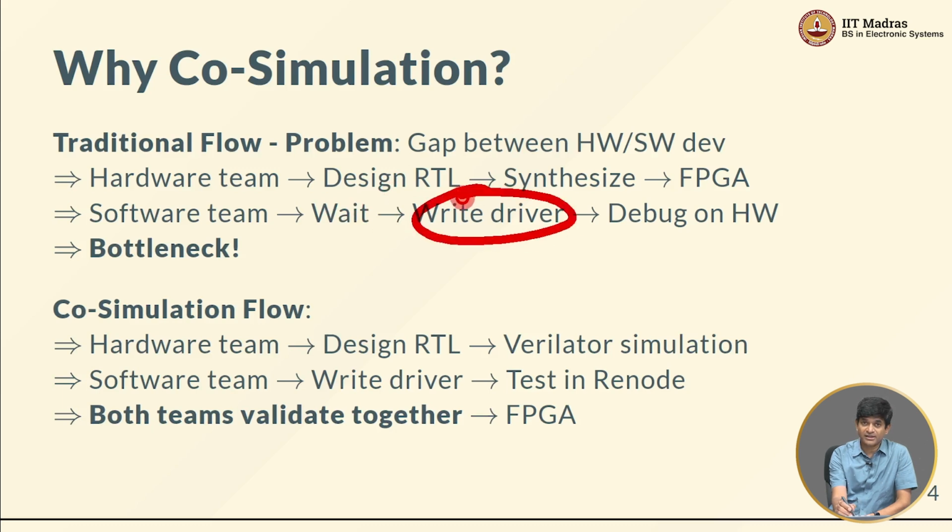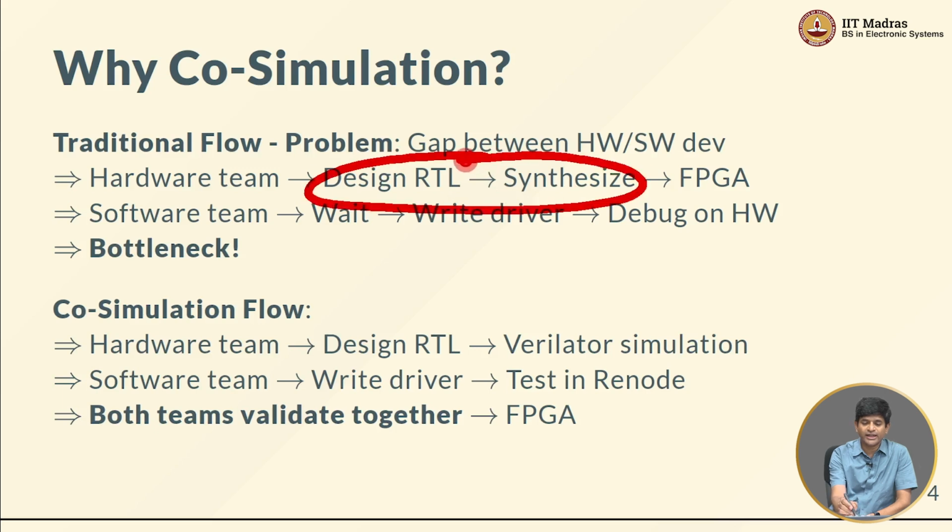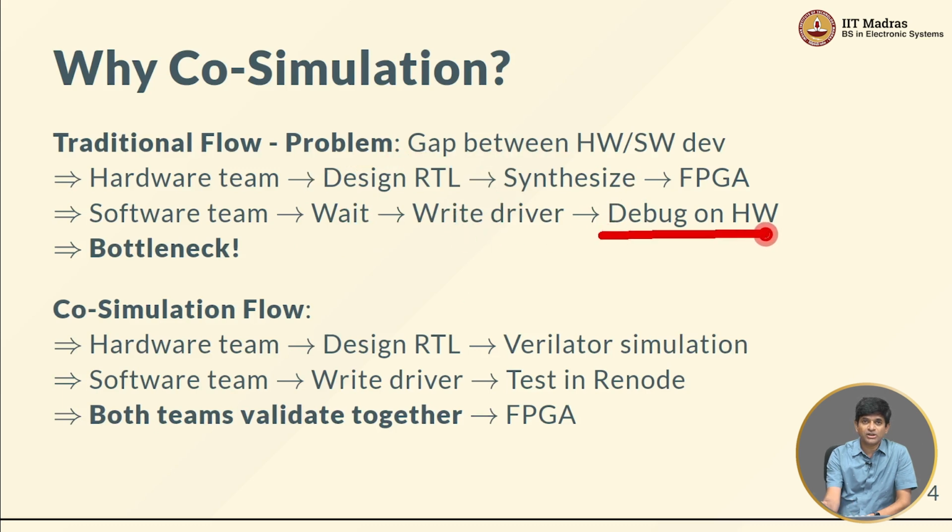But if they write the driver too early, once again they wait, because designing, debugging and synthesizing the RTL typically take quite a long time, right? So this ends up becoming a bottleneck. And finally, when you want to debug on the hardware, it doesn't matter if you finish synthesizing and putting it on the FPGA: unless you have a driver, you cannot debug on the hardware, right? So given that the synthesis and debugging process can take quite a long time, we would like to see, is there some way that we can break this bottleneck?